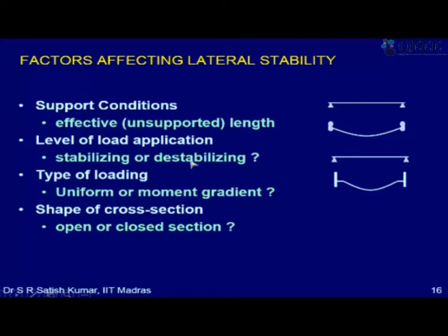So for analysis, we will assume the load is applied exactly in the middle, and with reference to that, we will increase the effective length, for example, to reduce the M critical value to account for the destabilizing effect of the load on the top flange, okay. That can also be done.